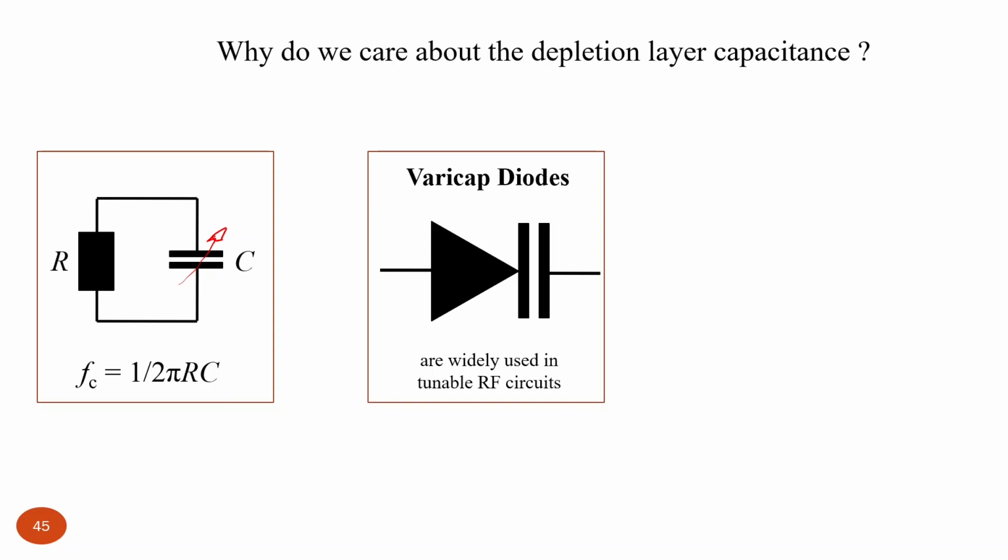And that can be done by just applying some potential difference between the electrodes of this varicap device, which is actually a PN junction made in order to have a large change of capacitance and thickness of the depletion region with quite low concentration of doping centers.